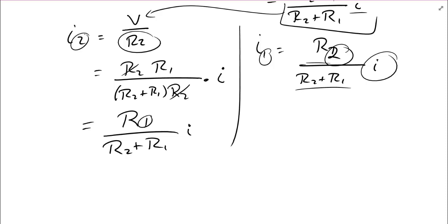Now, the important thing about this is that I didn't really bother solving for I. I could have done so by finding the equivalent resistance. But here's an example where it actually is far easier to just use current division, and that's typically when you have an actual current source, or if you know I in the first place.